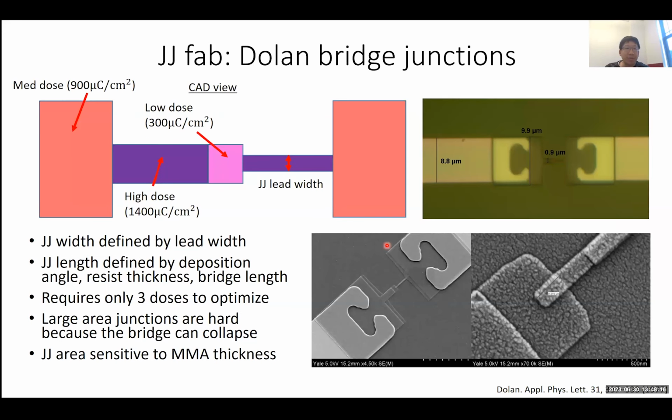So Suhas, maybe I missed this, but there's a related question. Would you have native oxide on the capacitor layer before making the junction? What do you do to ensure they have metallic contact in the notch shape you just mentioned? Yes, I'll go over the deposition process in a little more detail in the next few slides. But yes, in order to remove that oxide, you have to employ some sort of surface treatment, in particular an argon ion beam clean.